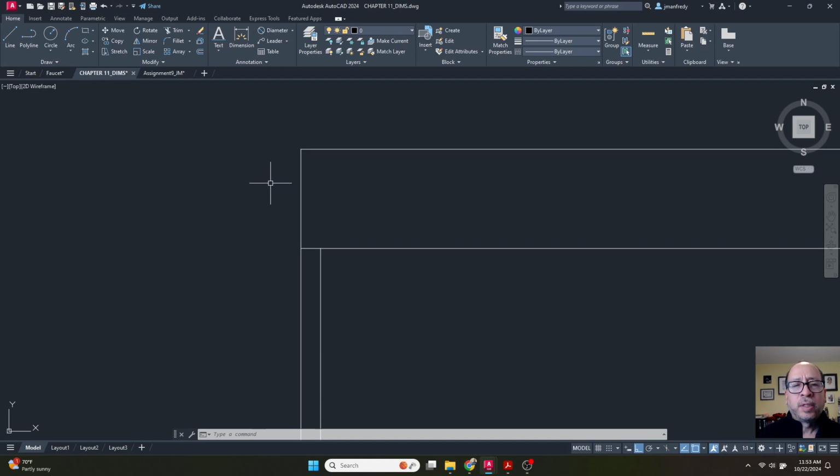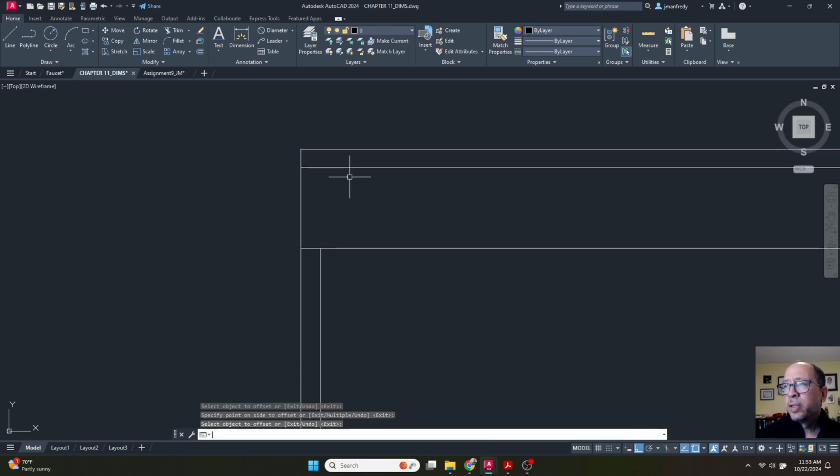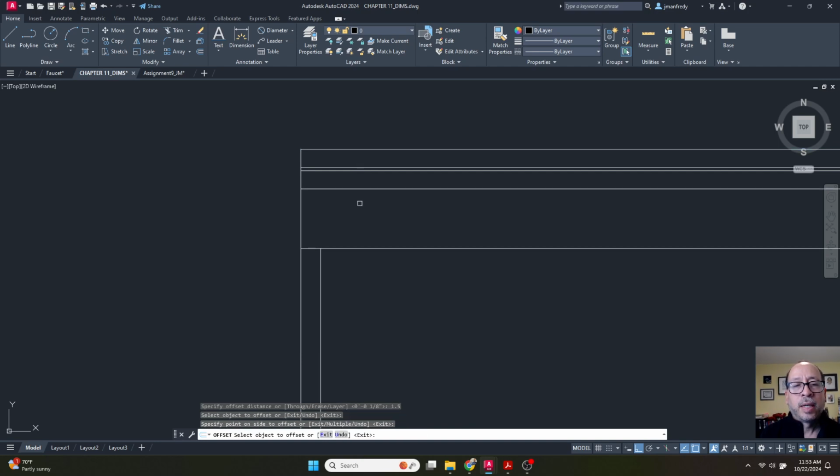This piece here has multiple parts to it. So the topmost part is 11/16. The next piece here is a 1/8 inch groove. Okay. The next part is 1.5 inches, so offset 1.5. This comes down 1.5 to here. Then there's a curvy piece here.